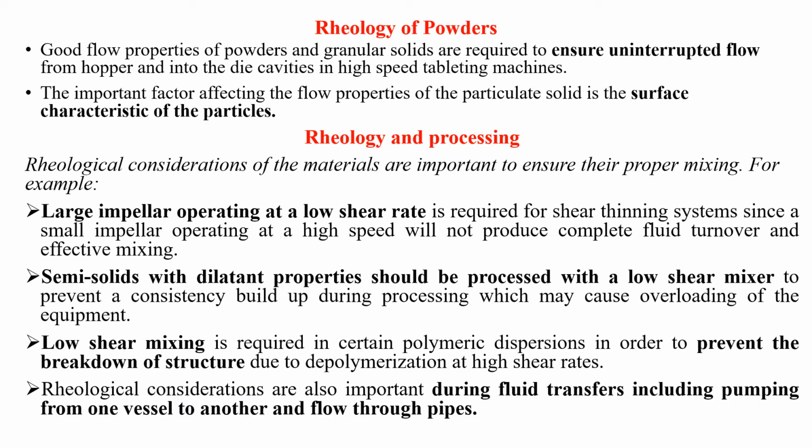And for powders, the flow property of a powder is considered as the rheological behavior of the powder. The surface characteristics of particles play a major role in determining the flow property or the rheological behavior of a particulate solid. The most important part is how this concept of rheology is applicable in the industry,